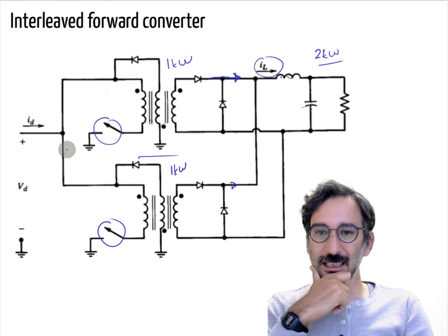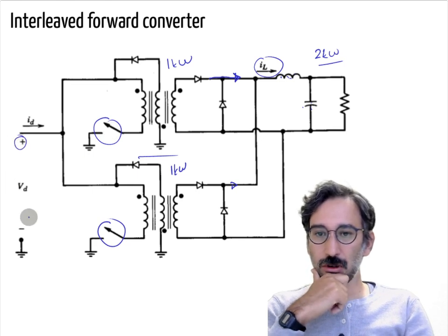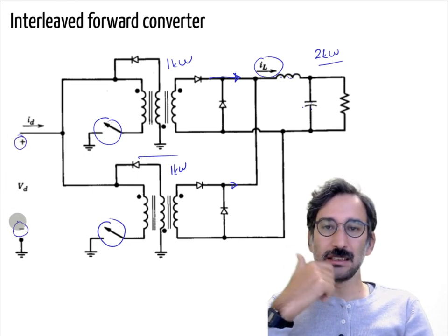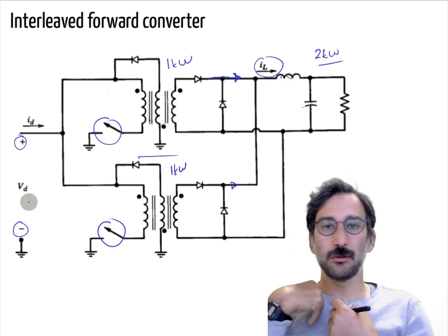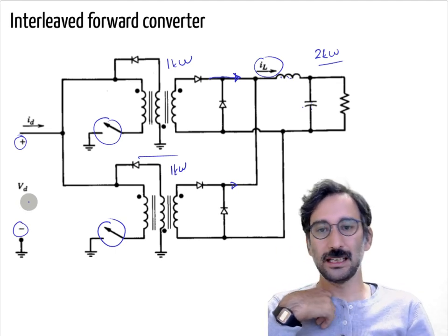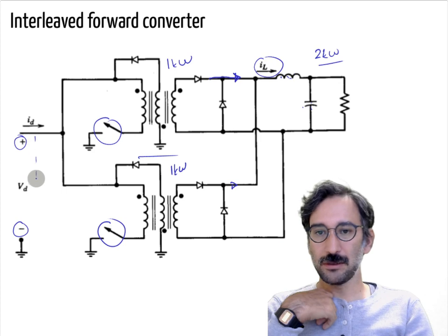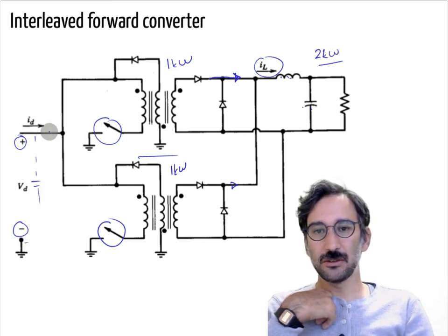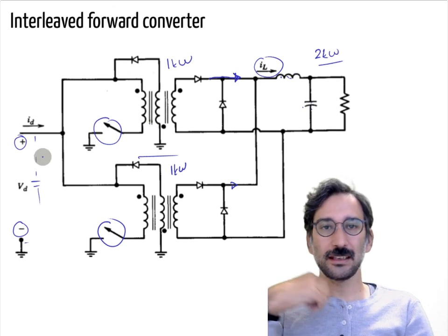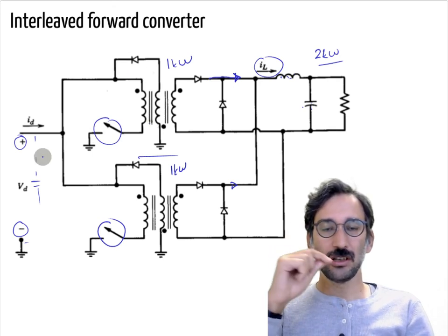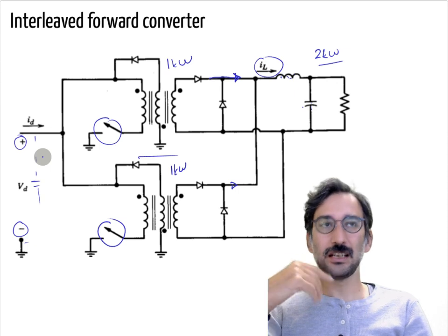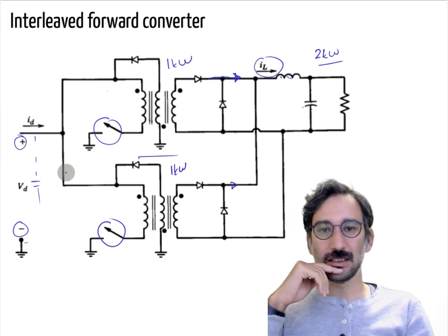Secondly, your supply is not always capable of absorbing power. Of course, you can put some extra capacitors, but that extra power flow from the third winding can increase the voltage on the primary side, or you may need to choose a larger capacitor.